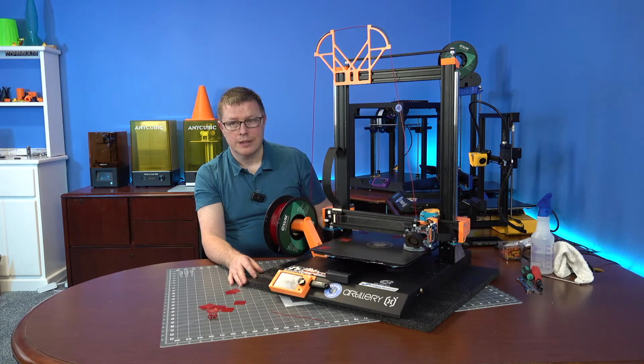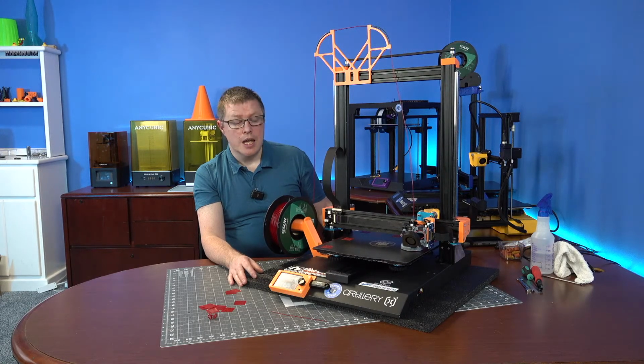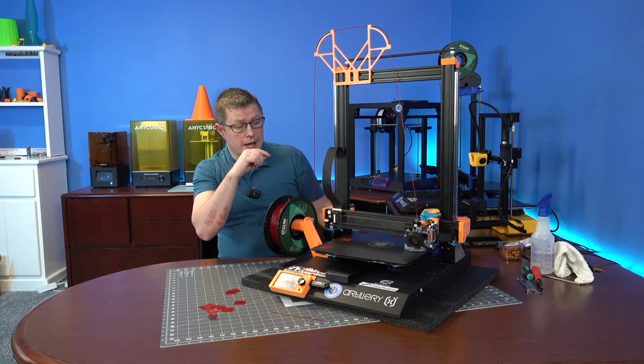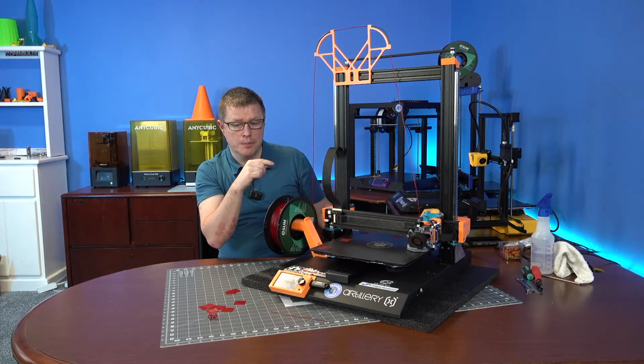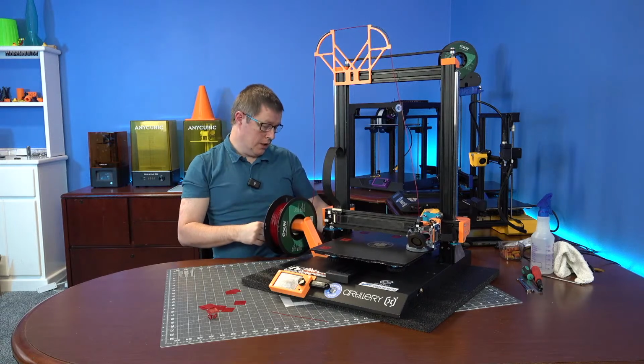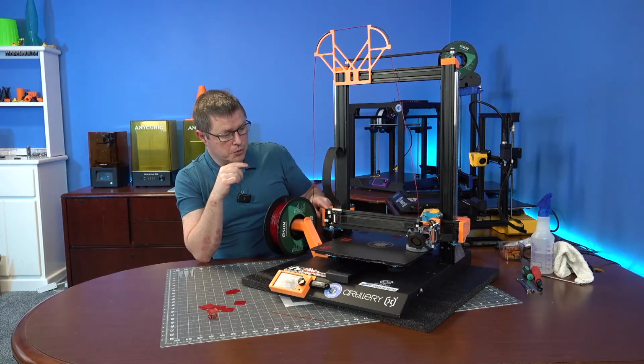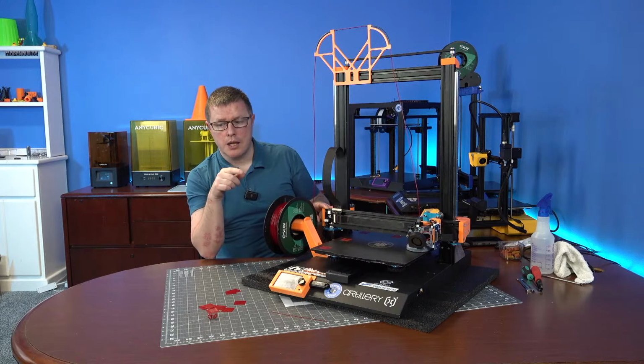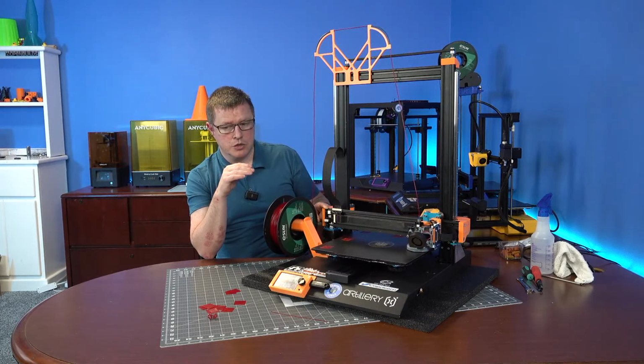Christopher says, can you talk about why your extruder board doesn't work with the X1 version 1? Is it a controller board incompatibility or one of the other boards? It is how they did the actual signal pathing from the connection on this side through the other boards. If you get a set of the version 4 breakout boards all the way through, it should work, because that signal pathing is set up in the breakout boards.